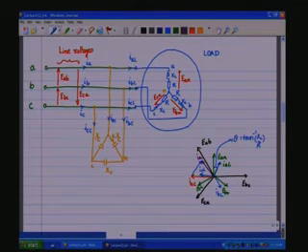If the capacitive network had not been there, IA would have been IAL itself, which is lagging EAB by a significant angle. But because we have put a capacitive network which is resulting in an IAC, a leading current, which combines with IAL, the load current, to provide a line current which is almost in phase with EAB.